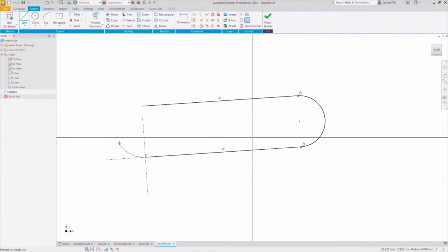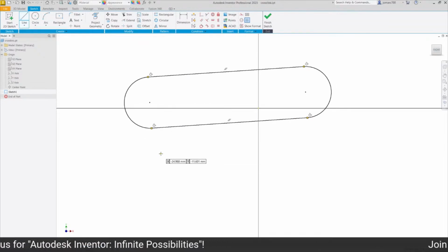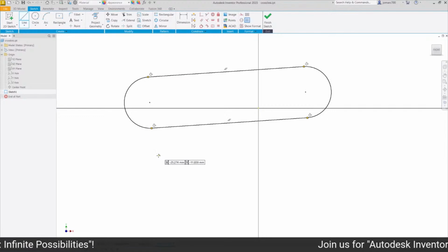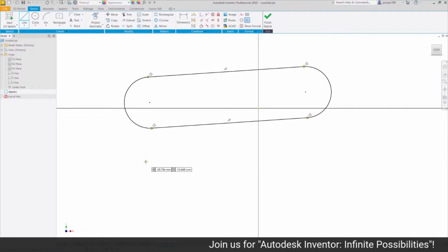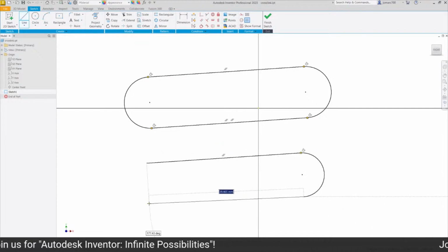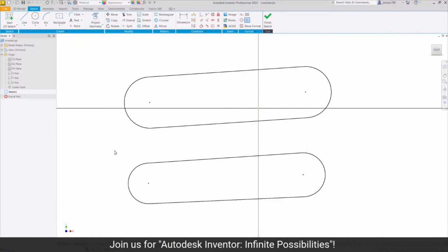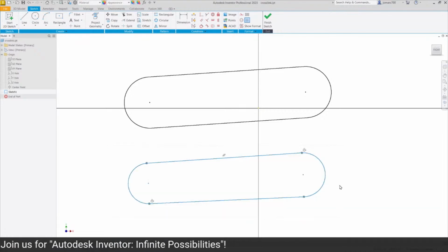Once more, I'm going to create another arc. Left click and hold, and connecting this point to this end point. So in addition, notice the inferred tangent constraint. I'm going to release. Okay, so I want you to practice creating an arc coming from a line. So once more, left click and hold, release, left click and hold, and connect this to the other end point. Hitting escape.